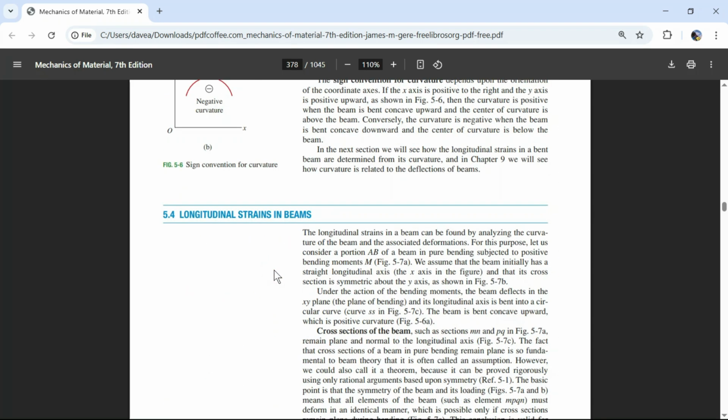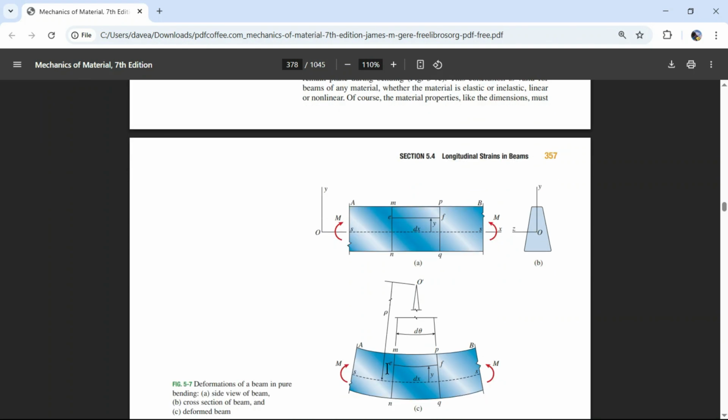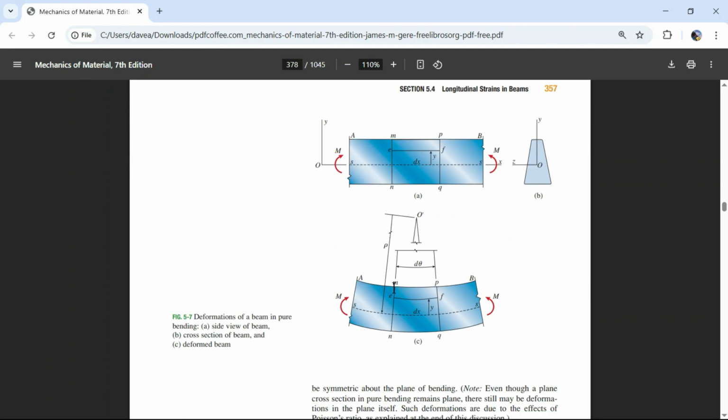And we prove that basically by taking a small little slice, and I like to think of this as almost a square chunk. Let's say the beam was only 4 molecules of iron, 2 tall, and we're just taking 2 molecules. The take-home point is that a moment is a load. It's 2 opposing forces. So to generate this moment, I apply a force arrow this way and then a force arrow that way, 2 opposing forces with a distance between.